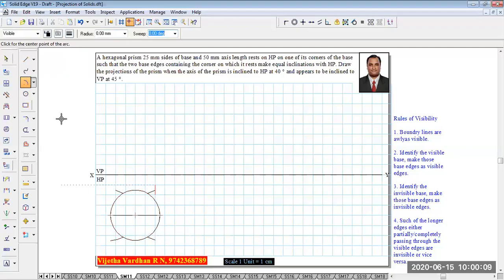Now, once you have these 6 points, that is, 2 points forming the diameter and another 4 points from the arcs, then using your HB pencil, make sure that you draw the hexagon like this by connecting the respective end points.